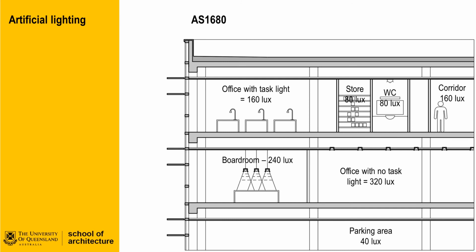The lighting level is a consequence of room size, room shape, orientation and so on, which in turn translates into a total illumination power. This illumination power is created by light fixtures and light bulbs that all take a certain amount of energy to run. Different light types consume energy differently compared to the light energy they produce. Compact fluorescent and LED lighting are becoming the mainstay of modern lighting design, as they can produce the light levels needed under AS 1680, whilst also complying with the total energy use under Section J. In addition to this, control systems that automatically turn off lights or automatically dim lights in rooms that are unoccupied all contribute to reducing the baseload energy needed even further.